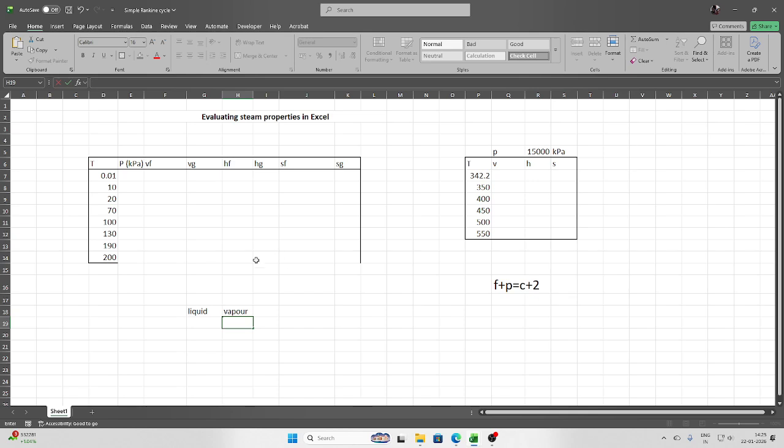Okay, so let us start with the saturation state first. Let's say I am interested in finding the saturation pressure. How to find saturation states? Simply, if you want pressure, then you will say P sat. If you want temperature, then you will say T sat, and so on. So P, then SAT, saturation. Now with respect to what you want, it is with respect to temperature. So you simply say T. Then pass this temperature and simply press enter. That's it. For every temperature you have that saturation pressure.